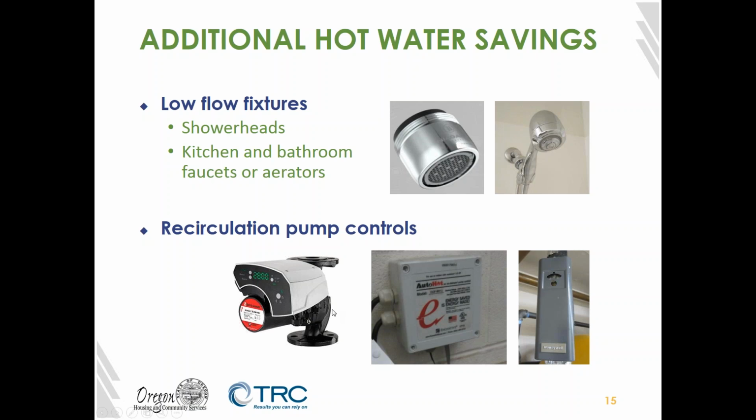and then turns the pump on and off accordingly. One thing to keep in mind for central systems is turning the water heater off can cause some crossover issues, which is where the variable speed pump is more useful because it keeps a constant pressure in the system to avoid crossover.